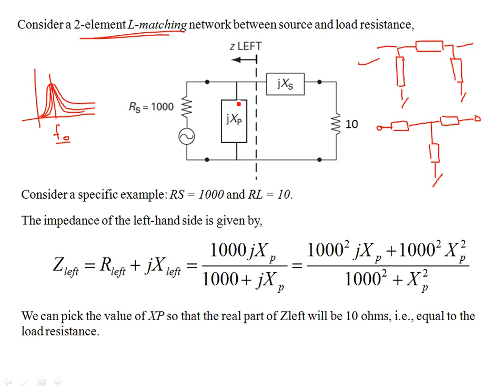Anyway, starting with the basics. You see these topologies can be derived from the basic two-element L matching network. For example, if you combine two inverted L networks, you can have an L network like this, and then another L network like this, having reactive elements over here. Whatever the combination of the series reactance is, it is combined to produce a pi. So a pi network can be obtained from an L network. This thing can be translated into this thing.